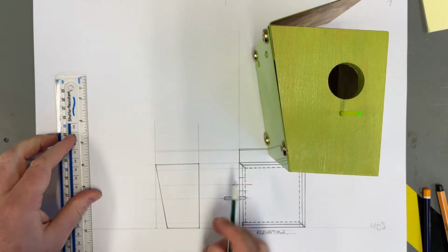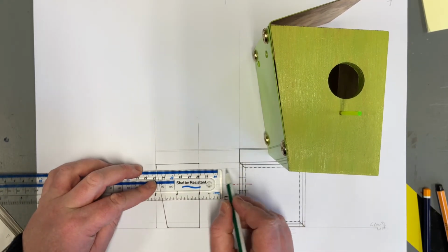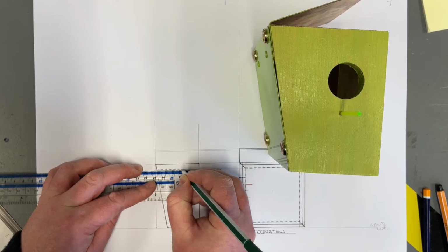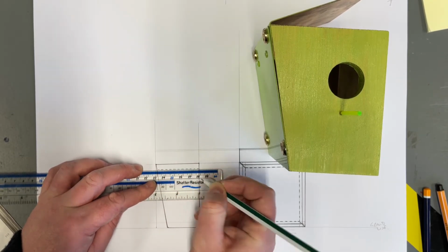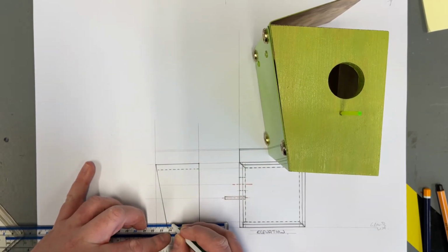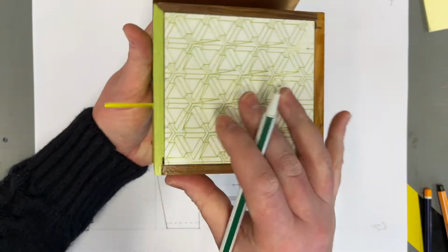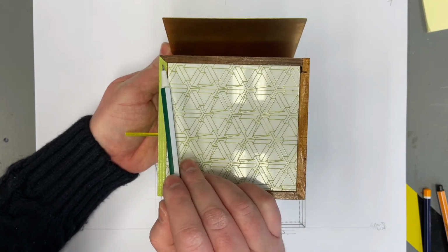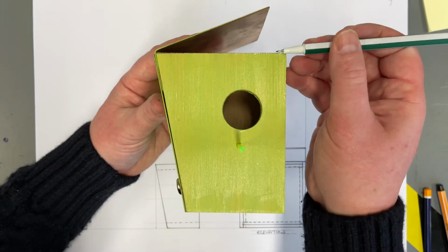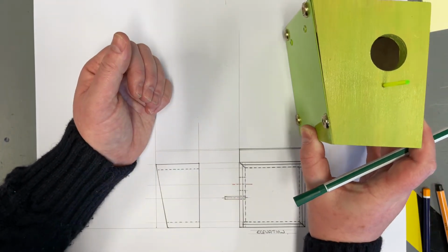Now we need to show the thickness of the wood, and therefore this line here, which is projected across from there, would be hidden detail. So that shows us that wood is 12 millimeters thick. And we do the same thing again at the bottom. And try to visualize this. Because we are not looking at the object this way around now, we don't see the joint appearing as such. We would just see it as a 12 millimeter line, just slightly beneath. Okay.